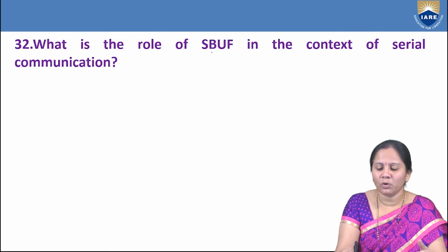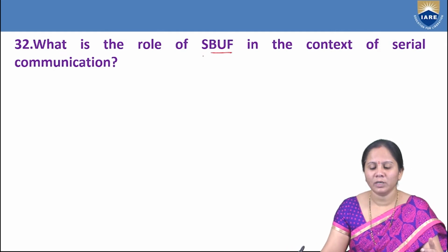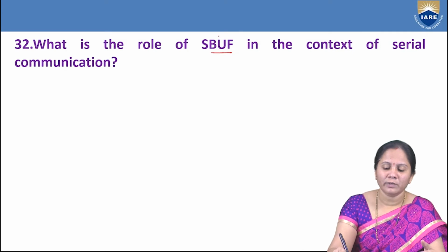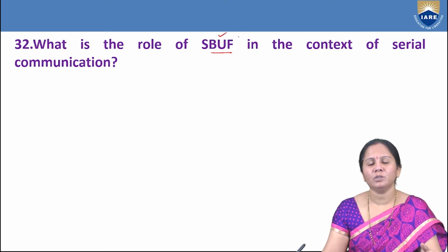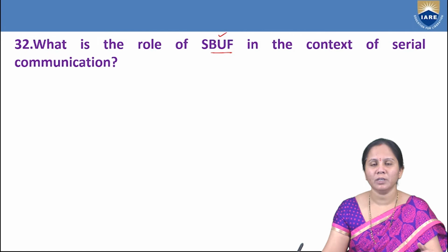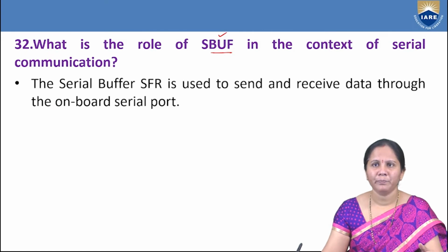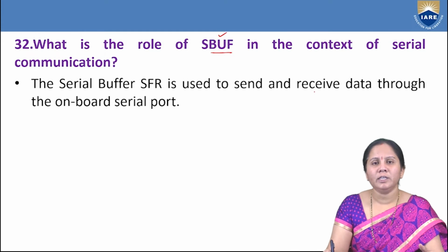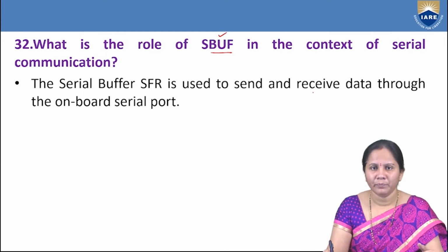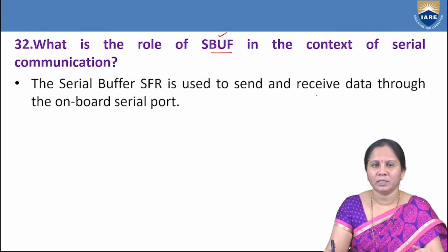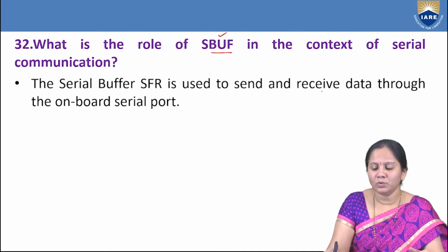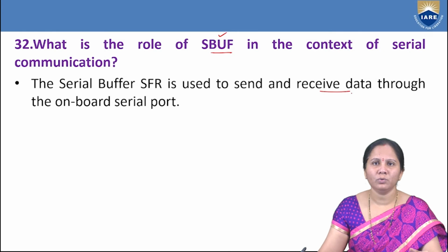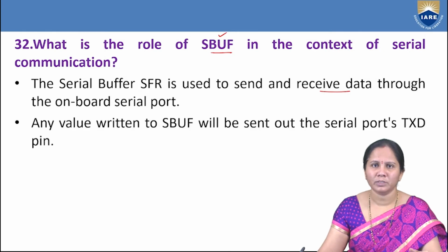Next, what is the role of SBUF in the context of serial communication? This register is also related to serial communication. SBUF stands for serial buffer. It is not bit addressable. It is a simple register available at the transmitter end and receiver end. It is used to send and receive data through the onboard serial port.